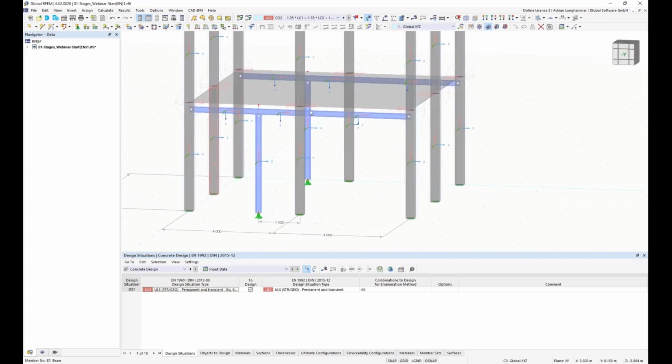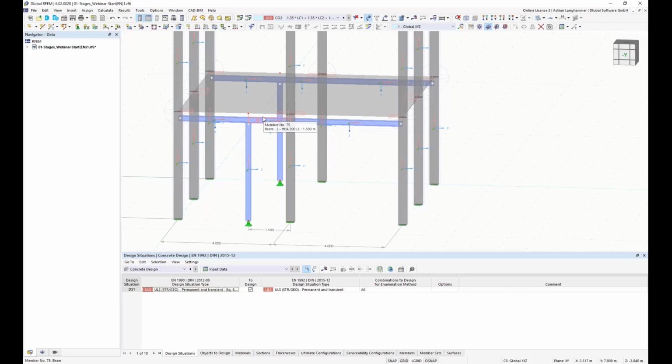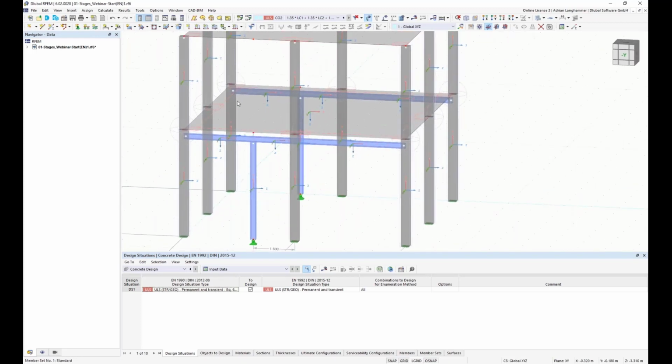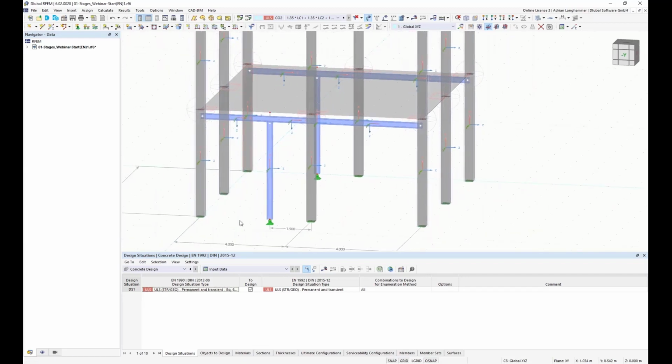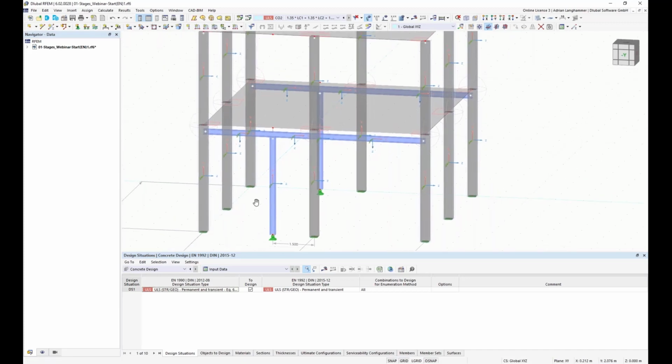Since the steel girders are applied afterwards for the existing structure and below the concrete slab, I would like to assume that not all forces are transferred from the slab to the girder. And to consider this, I also will add line hinges to these lines here at the edge. And this line hinge should only transfer vertical forces in positive z direction or in direction to the ground.